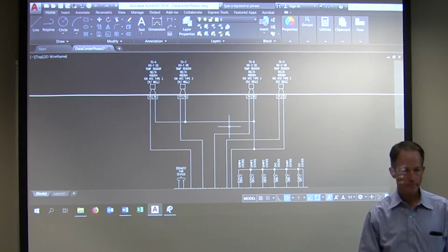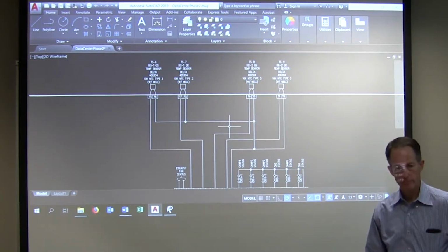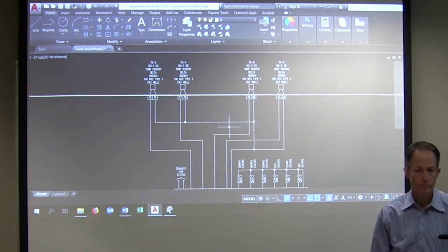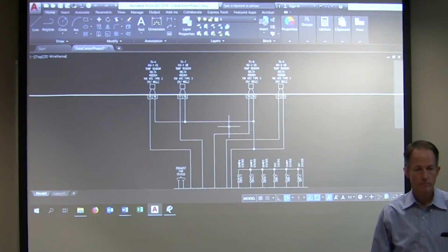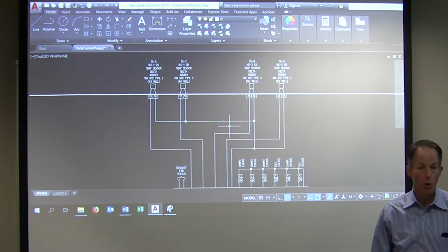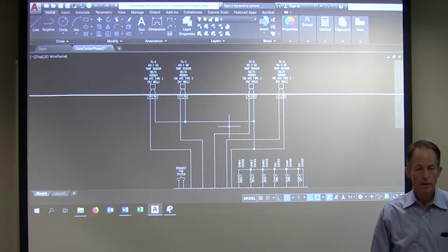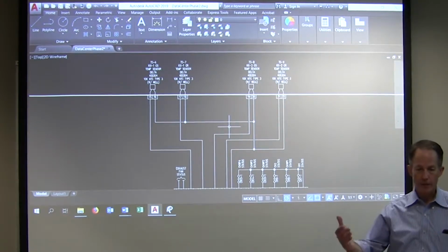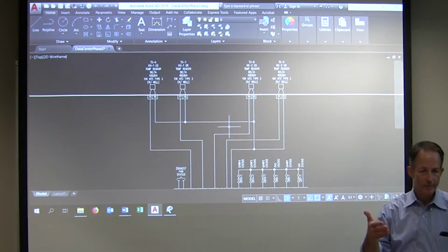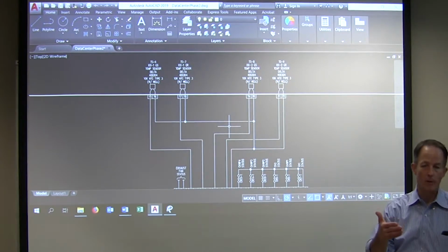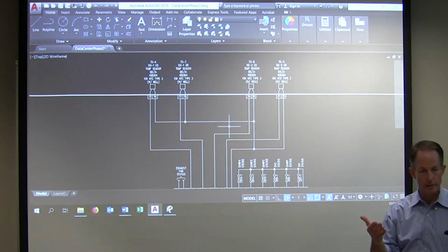Can that wire going far away, touching different temperatures, make a change in the resistance? It could, yeah. If the wire is either hot or cold, that can change things a little bit, depending on the areas that you go through. But if you're doing 500 feet, and you're probably a little bit more than that, it's probably more like 5 or 6 ohms is all you're going to see.